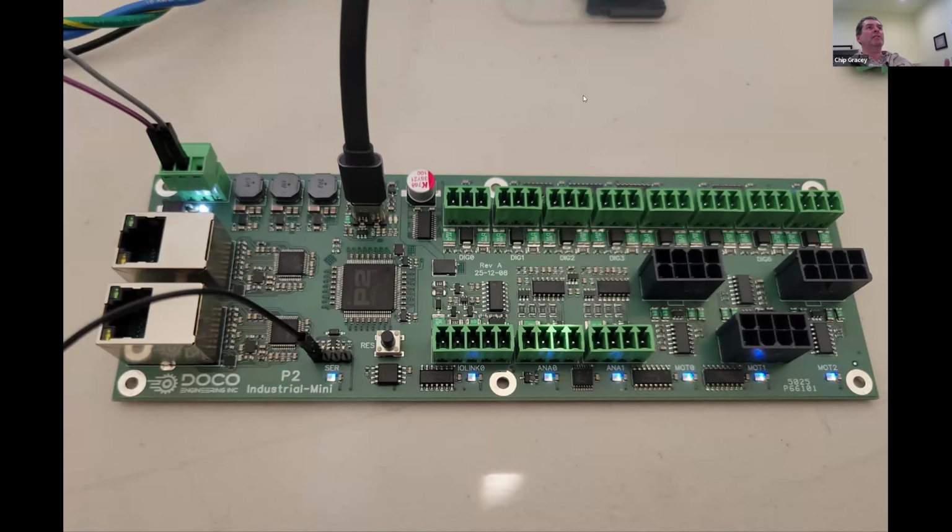So we can also sink and source an amp briefly or a half an amp at 24 volts continuously through this thing. So you could use these for sensors, for driving stepper motors, for sending higher current 24 volt signaling all over the place. And then we have 3. First, before we embarked on this, he had me develop a lot of jerk-based motion control code.